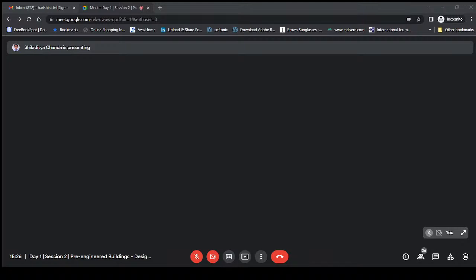For the intermediate support, some lap is provided. For the normal case, from the center to this place is 300, and from the center to this place is 300. So a total of 600 mm lap is provided for a normal intermediate support. For the last but one support, it is normally provided as 600 on this side and 300 on this side. This is how we take care of the extra bending moment coming over here. I am sure you must have learned the design of continuous beams in your classroom. So this is a perfect example of how you can implement your classroom teaching in pre-engineered buildings.